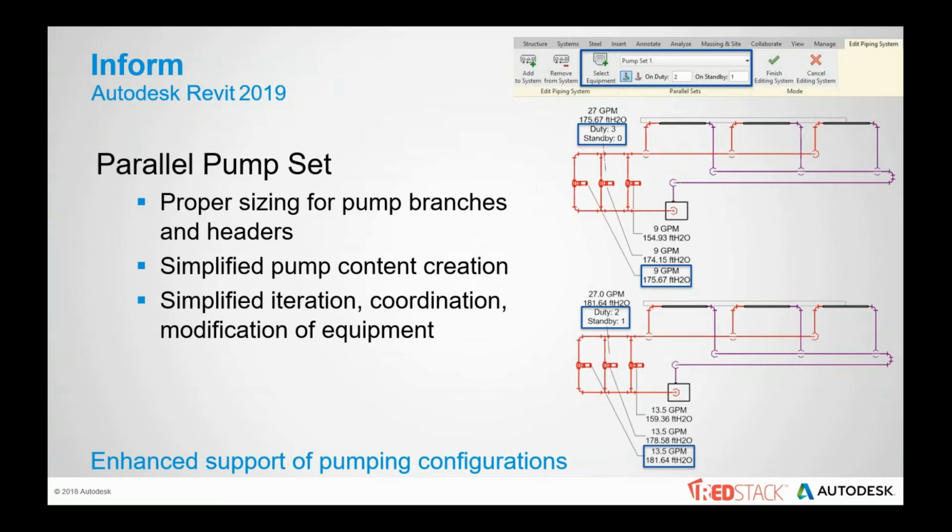Sorry, guys. So you no longer have to deal with flow factor or fiddle with connecting things in a certain order to hopefully get flow to propagate through the pumps. You can set up and analyze pumps in parallel in hydronic pumping networks, easily compute flow from duty and standby pump quantities. You can set up and analyze pumps in parallel, and it's got enhanced support for pumping configurations.